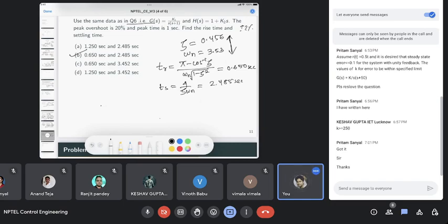Your standard formulas are applicable only when you have a standard signal, right? Your r(t) is not t only; it is half t. So in that case it will be better to write the error signal directly from the transfer function, and then there will be no confusion. So you write the closed loop transfer function.